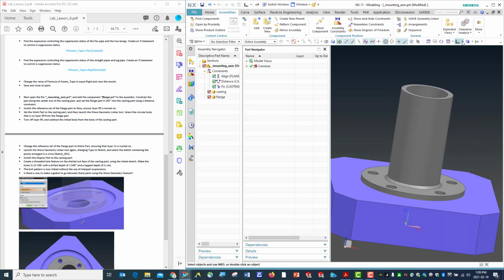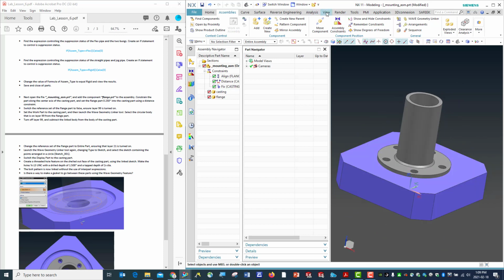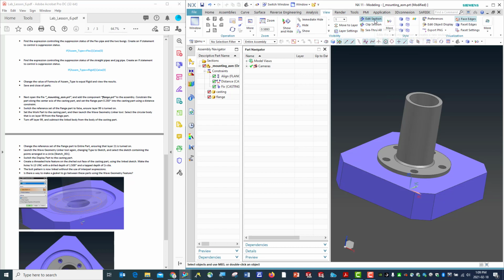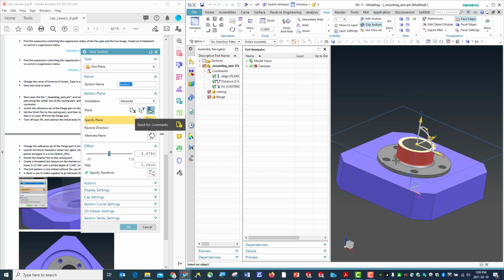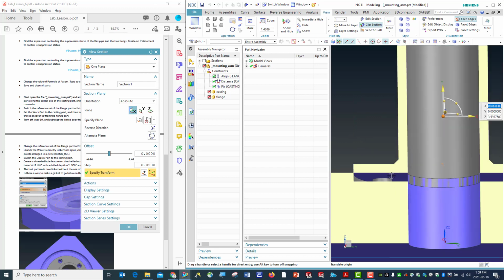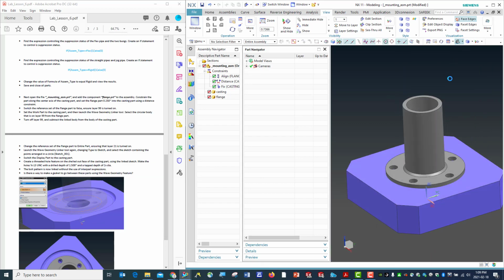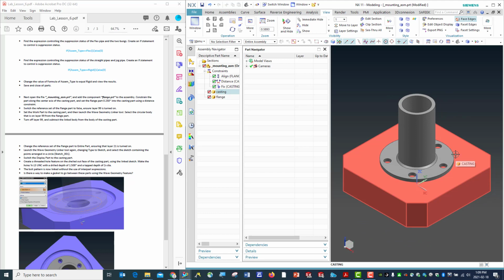All right. How do you know this is going into it? It's difficult to see it, right? So what we can do here, we can use section view. Okay. So you should be able to use this. Okay. So I'm going to use X. You can see here, right? So there's an overlap, right? So that means this face is a 1/4 inch below this top surface. Okay, so I'm going to cancel this one without any section view. All right, so what's next?